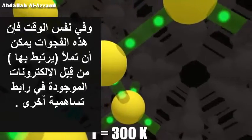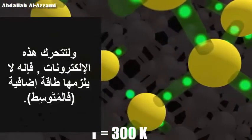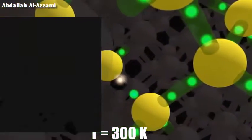At the same time, the broken bonds can be occupied by electrons from other bonds. For these electrons to move, no additional energy is required on average. This broken bond or new state is termed a hole and behaves as a particle of positive charge and mass.